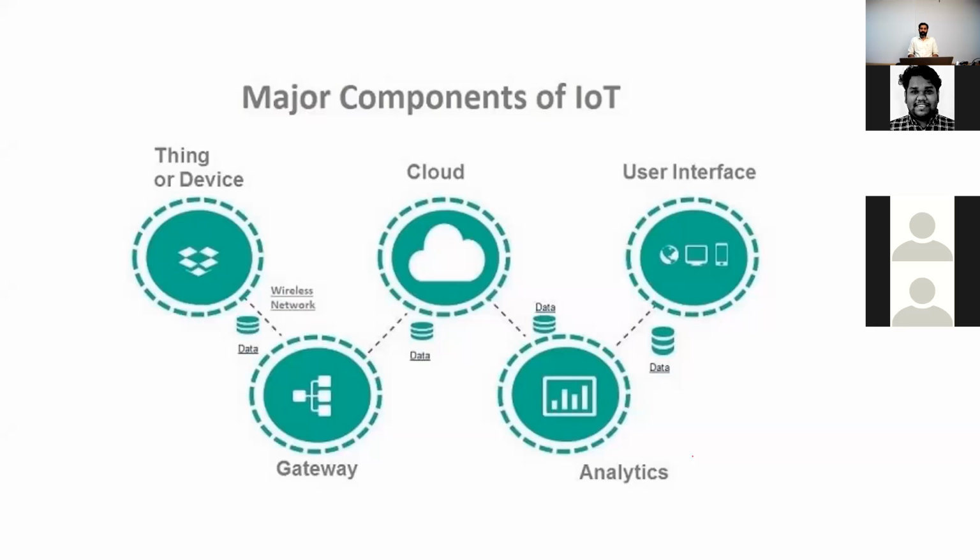You know that the structure of your data packets will have some meaningful information or sensor data along with some error correction bits, then start bits and stop bits, etc. As compared to the data packets in your local area networks or wide area networks, it also has the same format or frame structure. Similar to that, the data from your digital sensors can be connected to your microcontroller by using serial communication protocols or a two-wire communication protocol.